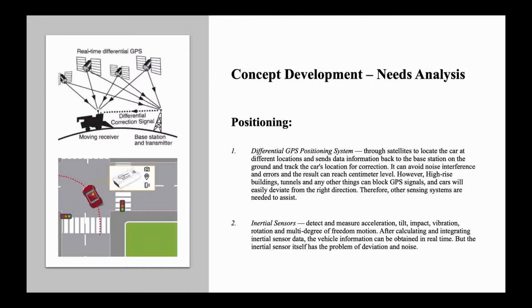The second is inertial sensors. They can detect and measure acceleration, tilt, impact, vibration, rotation, and multi-degree of freedom motion. After calculating and integrating inertial sensor data, the vehicle information can be obtained in real time, but the inertial sensor itself has the problem of deviation and noise.